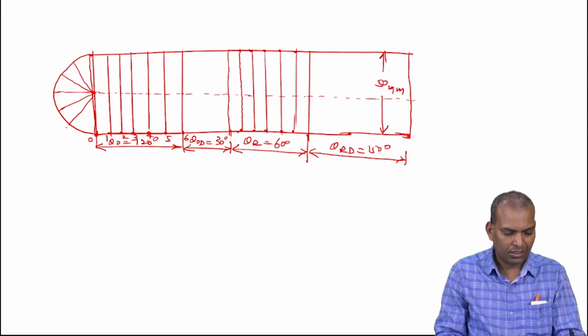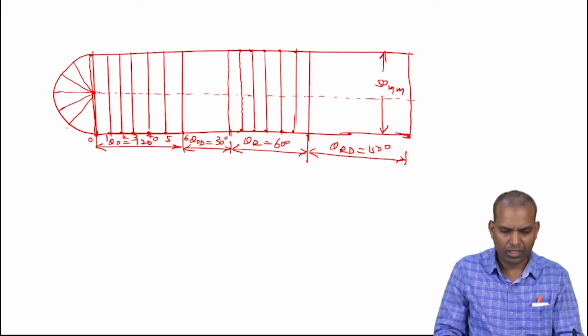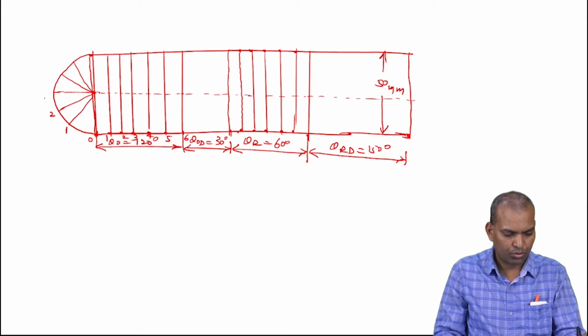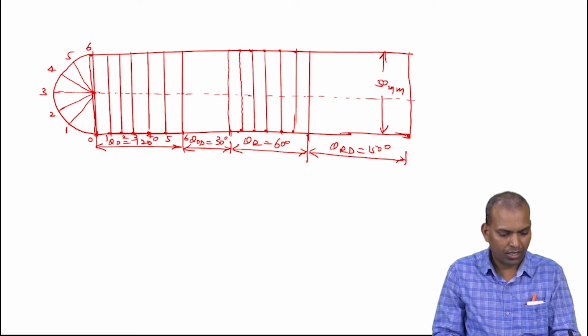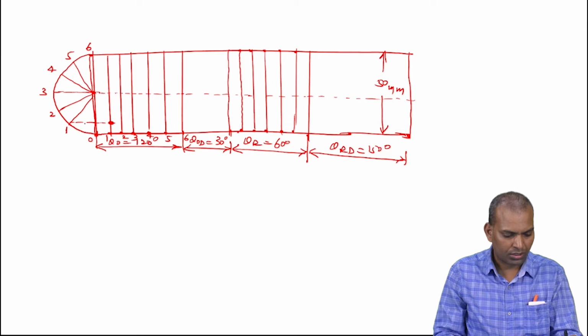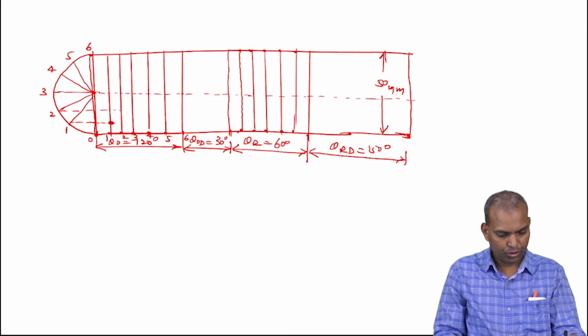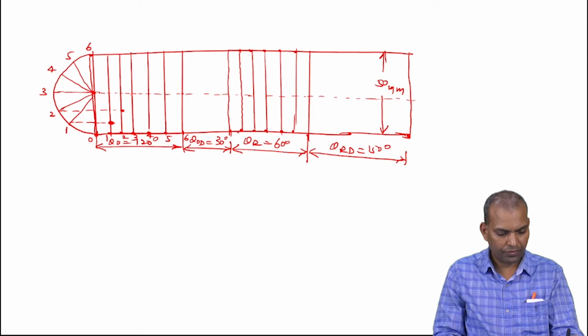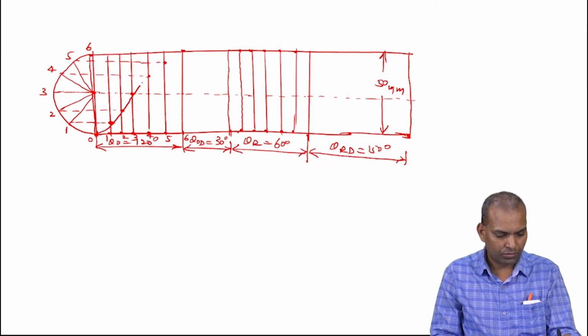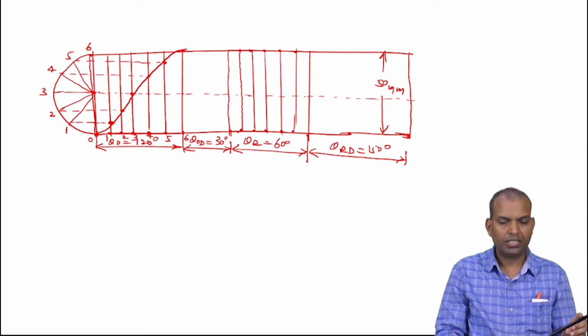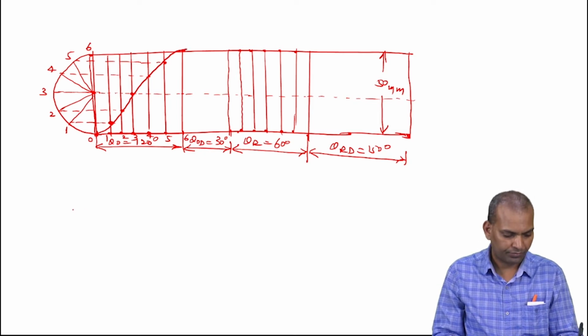You mark it as you like, you can change any letters. I am taking 1, 2, 3, 4, 5, 6. So draw a horizontal line which intersects at 1 with 1. This is the point. Next 2 with 2. Next 3 with 3. 4 with 4. 5 with 5. Join all these points with a smooth curve. That curve indicates the SHM curve.